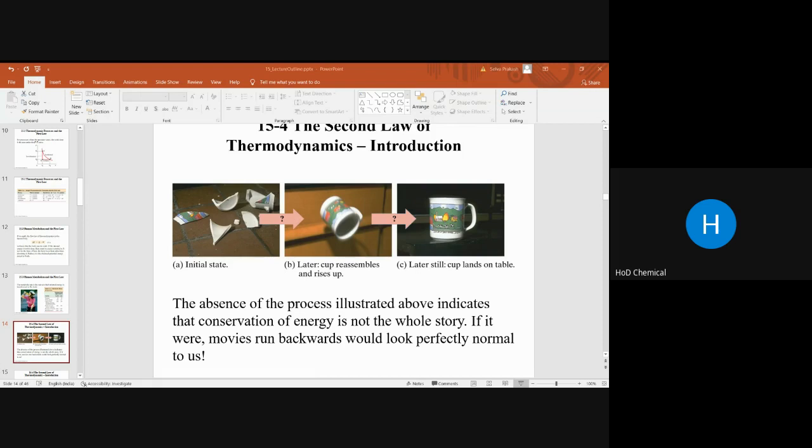W is QH minus QL, so e equals (QH minus QL) divided by QH. Further simplified, e equals 1 minus QL divided by QH. We can cross multiply to get the previous equation.